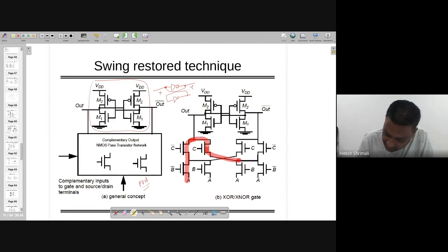So this particular node has, right? So this red connection connects to out. So in that case, what is out equal to? You can see here, B bar ANDed with C bar and ORing with C, okay, I forgot to take this A also. So first of all, this becomes A, B bar, C bar, right, which is here. In this case, it's a parallel connection, so it's OR C times AB or A bar B bar. Note that everything has to be complemented.